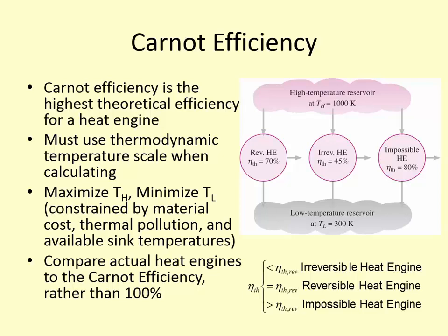And so a lot of times we think that's the benchmark. Well, everything should be 100% efficient, but theoretically, we cannot do that when we're converting heat back to work. So don't look at 100% as the goal. Look at the Carnot efficiency as the goal, and then that makes it a lot more reasonable when we see this is the best that we can do. We're at 55%, but Carnot efficiency is 60. Okay, well, we're close. You know, that's similar to having 95% versus 100.